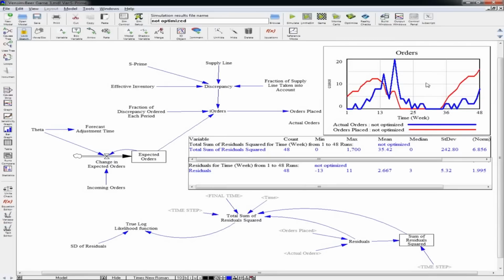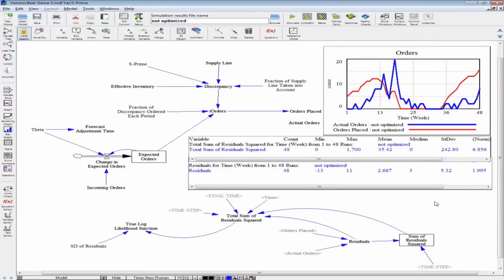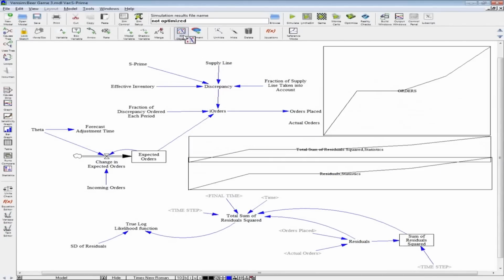We can see that although the trend is generally correct at the high level, the shape is totally different. This necessitates the question, how can we effectively measure the fit of the data? The typical way is to calculate the sum of squared errors, which are differences between simulated and actual data points, squared to make sure negative values don't reduce the total sum. The basic statistics of any variable can be found by using the statistics tool from the Output Workbench tool.